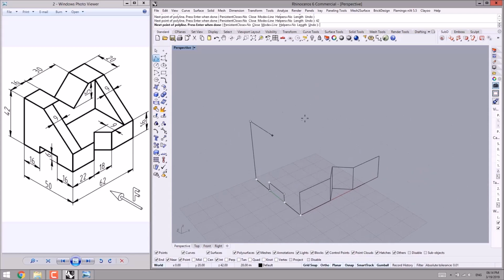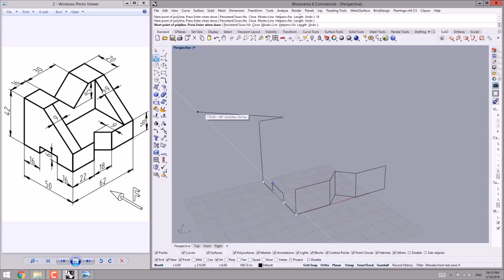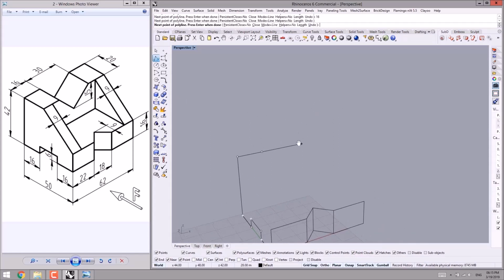Then by holding down Control, I sketch the vertical line. I hold down Control, then by click and drag 42, the total height. And then for this part, as you can see, I import 16. As you can see, there we should define an angle length. The total length there is 30. I mean 15 for its sides. I import @ for defining the angle. I'm sorry, for the relative coordinates.